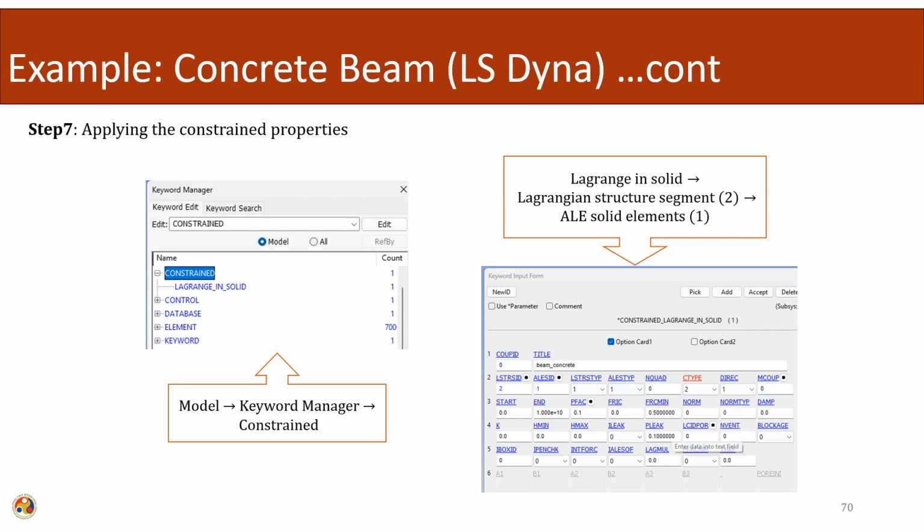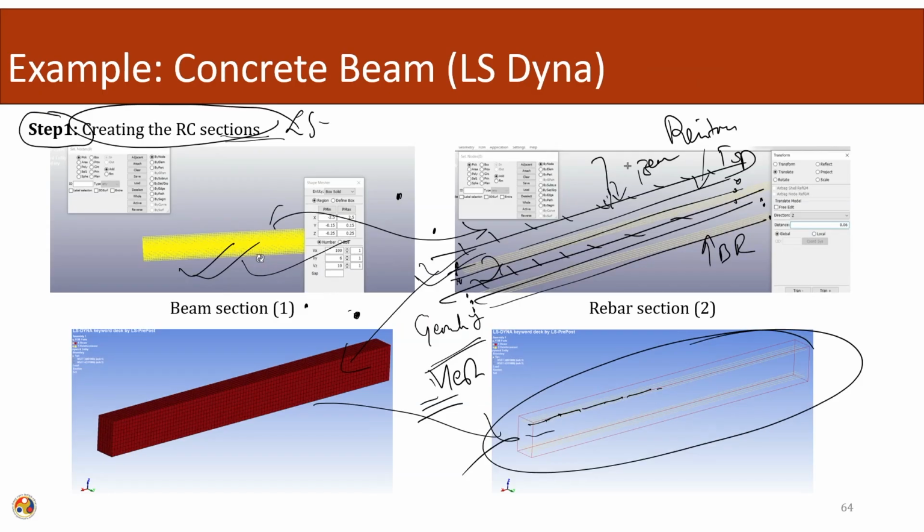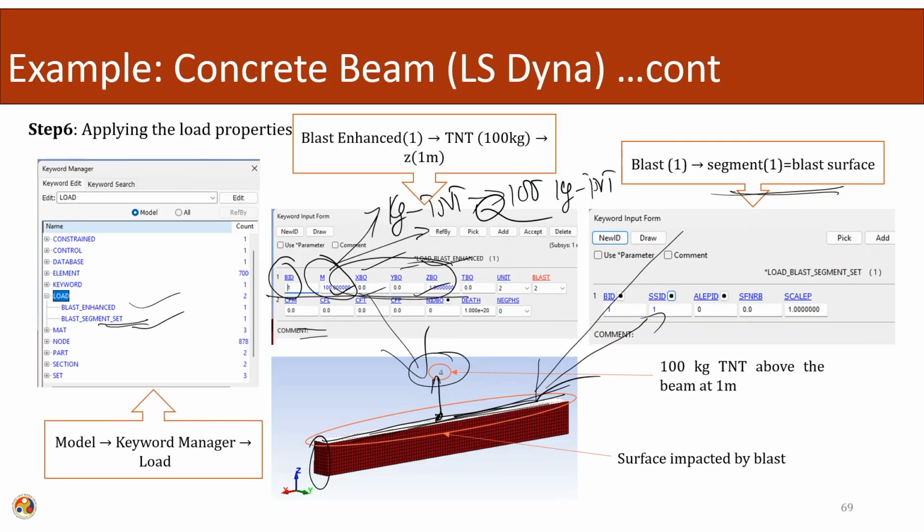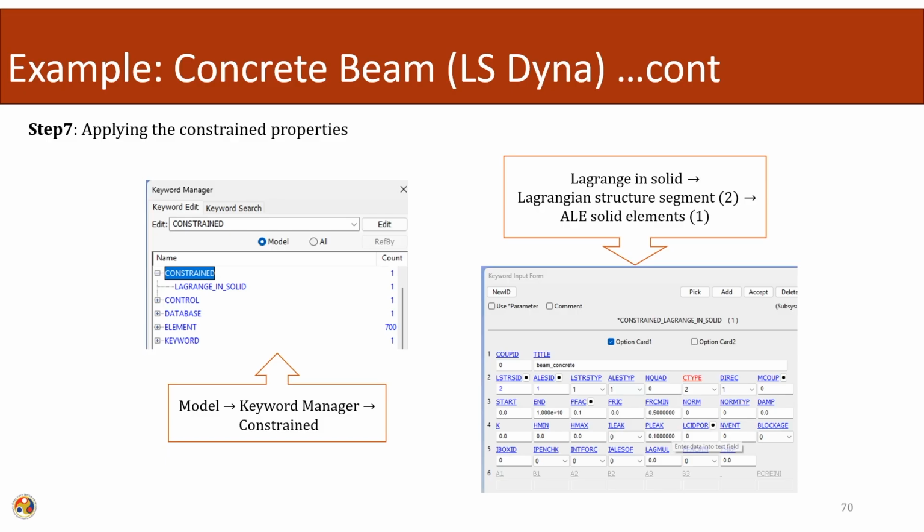After the loading, remember we modeled it using an RCC beam. While modeling, we just made the sections. We made one concrete section and we kept the rebars here. We did not tell what the interaction between these two is. So here we now need to tell the software what the interaction between the two is.